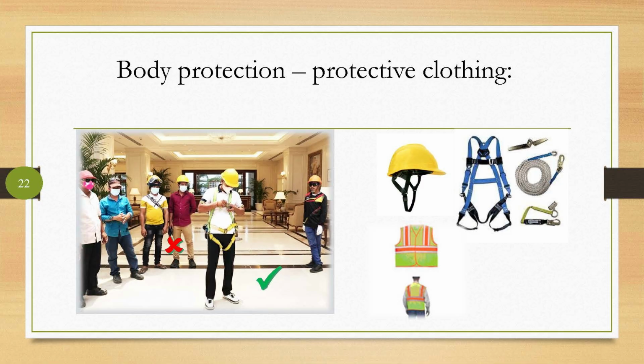Workers should wear safety belts or harnesses for fall protection on site. These must be clipped when working at heights greater than 1.80 meters. A high area means a free fall of 1.8 meters or more, measured from the feet of a standing worker to the floor or ground.